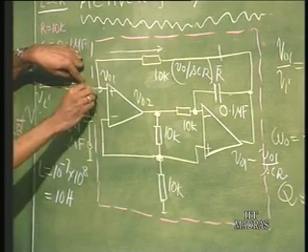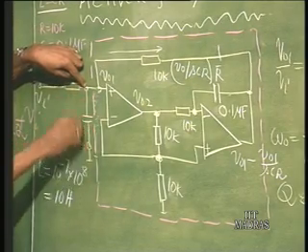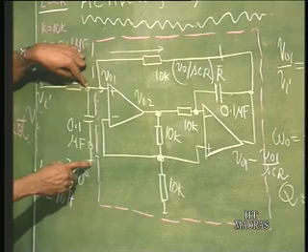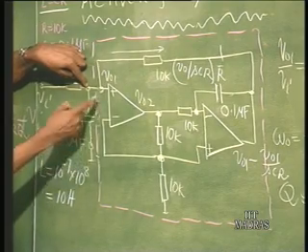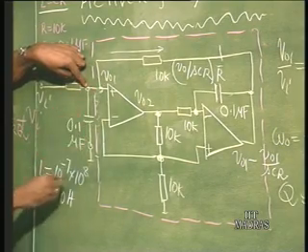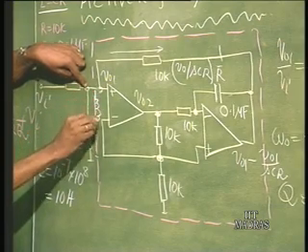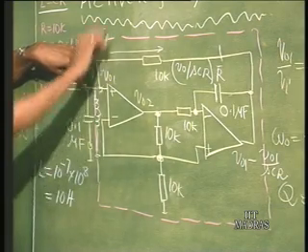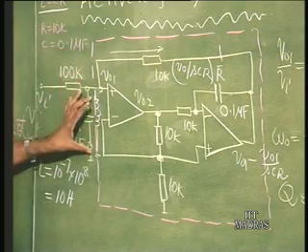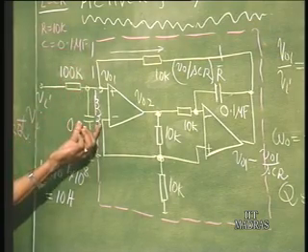That is therefore going to be having a capacitor across it. So, you have an L which is 10 Henries from here to ground, and then we will put that L that is simulated by this circuit, and a C across it. This is called a tank circuit.